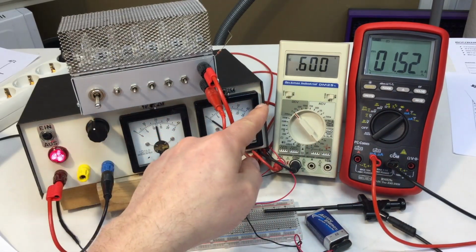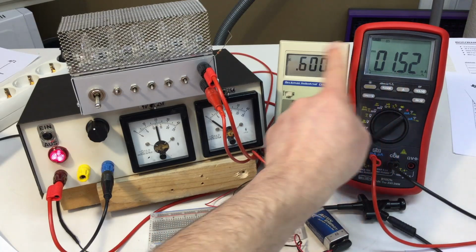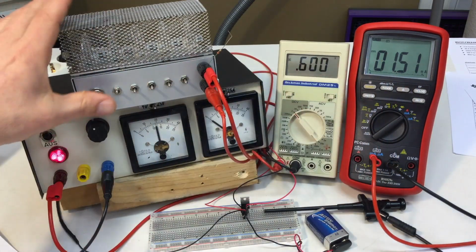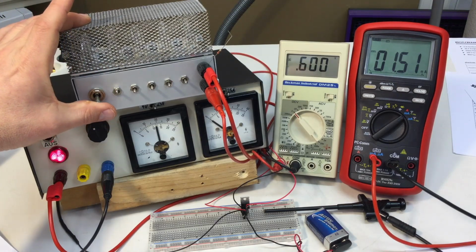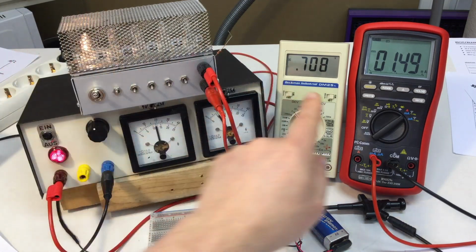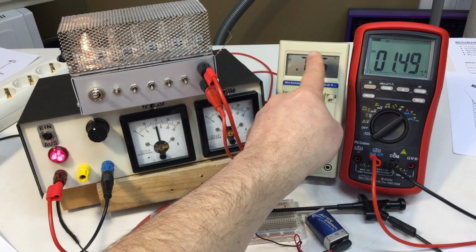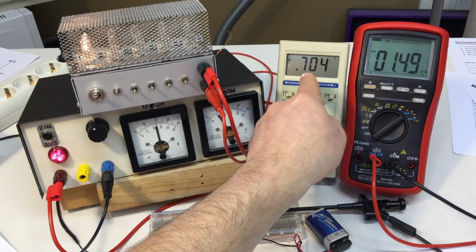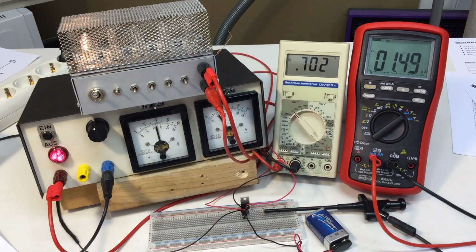And there's another effect I want to show you. We are at the 1.5 milliamps and 0.6 volts, but I have cut off my load circuit. If I switch the load circuit on, of course it latches, but the voltage across the gate makes a little jump from 0.6 to 0.7 volts.